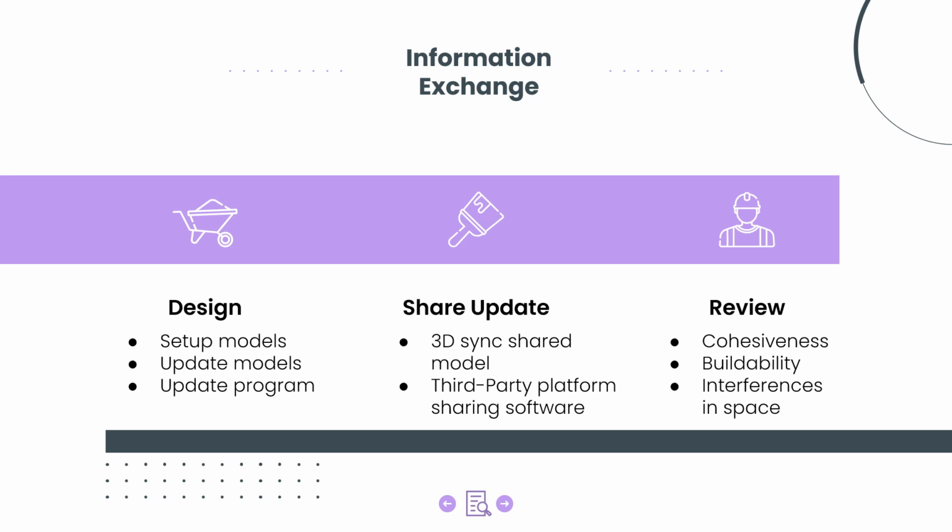The different steps are: information exchange worksheet, identify each potential information exchange from the processes; choose a model element breakdown structure for the project; identify the information required for each exchange, meaning input and output, and compare input versus output content.